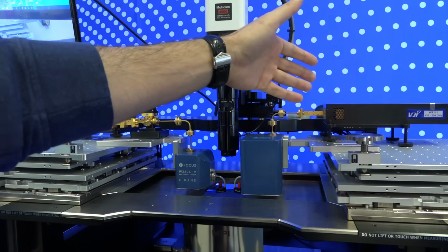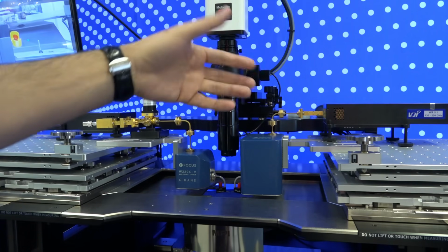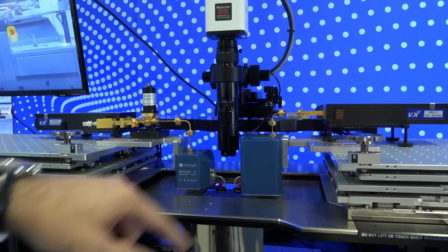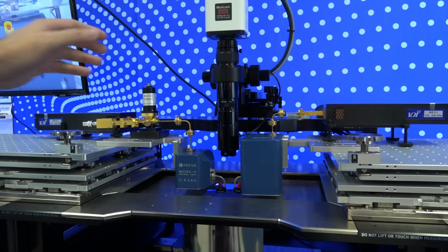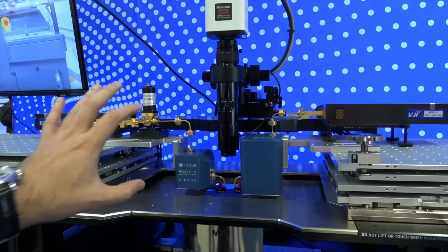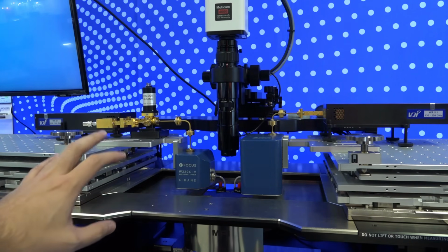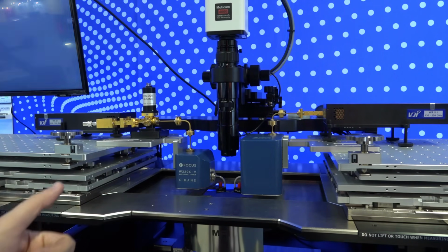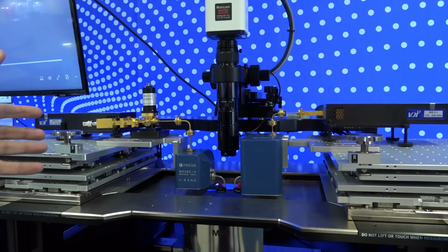So depending on the head that you are connecting on the other side, you can have down conversions to different frequency bands. So in this one compact setup, the key is that because of the automated switches and everything completely being in place, you're not changing the setup at all between doing your noise figure measurements and noise parameter extraction, as well as the S-parameter calibration. It's done all in one step. So allowing you to do these really, really broad noise figure characterizations.